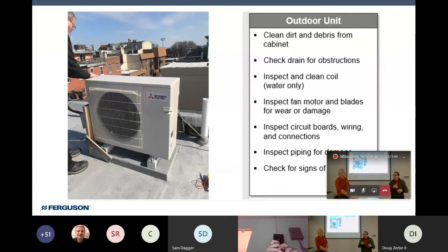All of a sudden, when the water drained out from between the insulation and the piping, which was wicking off the BTUs, we watched 45 degrees leaving, 47 degrees. We came up 7 degrees in our temperature just by getting that water off. Right. So that's what I'm just saying. Insulation and visual inspection of insulation is really critical. Right. And those are some of the things.